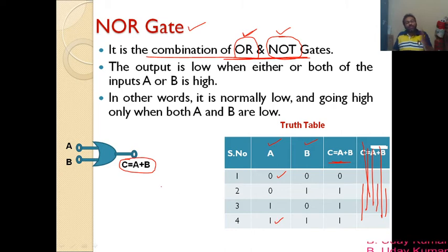So anyway, you can apply low and high potentials to both input terminals, and the possible combinations will be 00, as you already know, 00, 01, 10, and 11. So if I apply 0 potential to both A and B, the output of the OR gate will be 0.